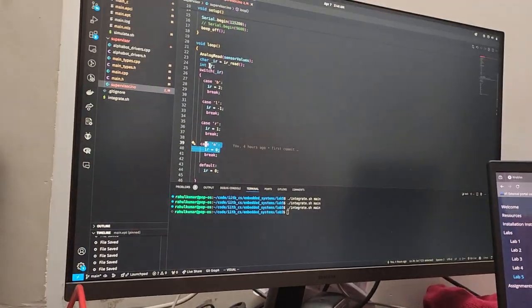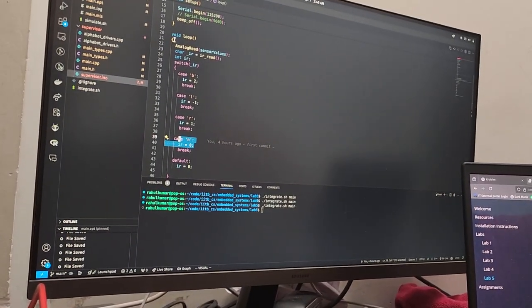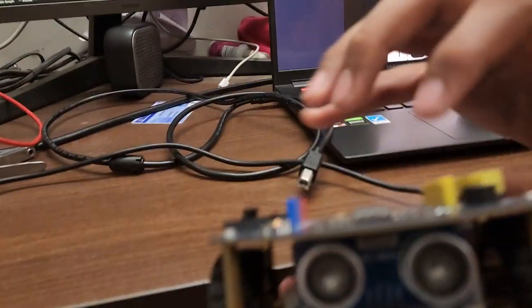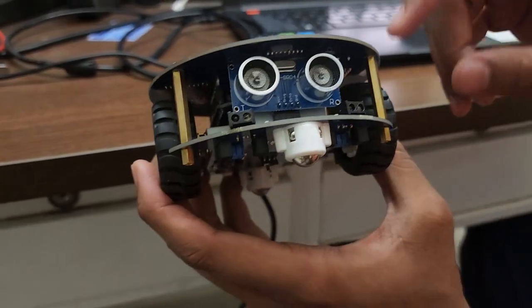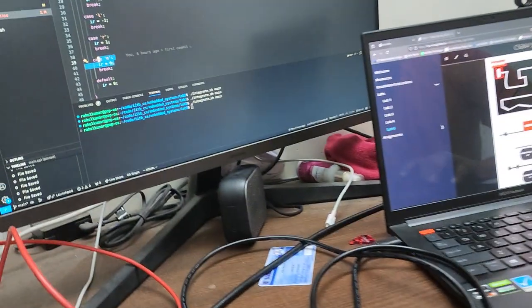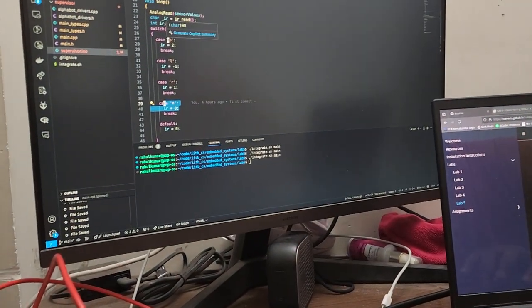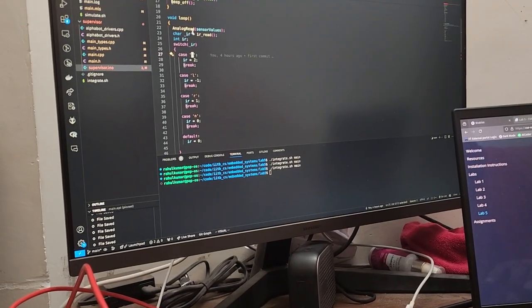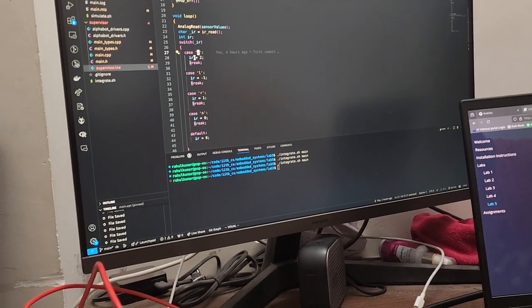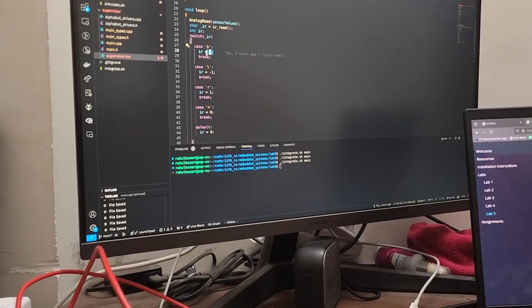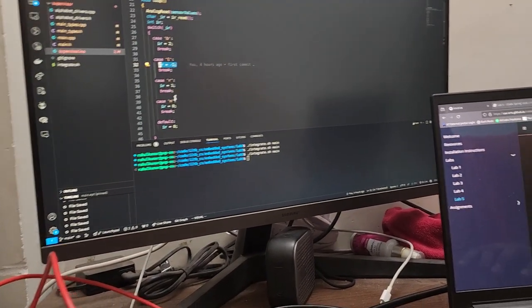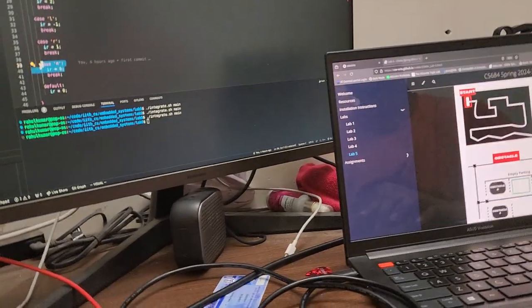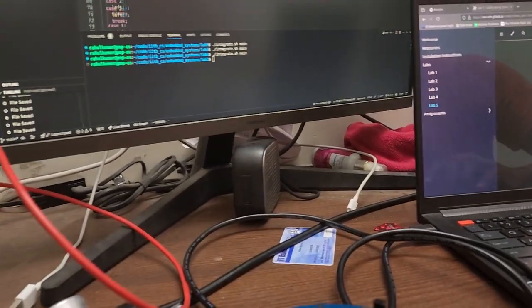Over here in supervisor.ino, this is the ino file which will be dumped on the bot, and we are not using any other sensor, we are just using what was already provided. These 2 are the IR sensors for proximity checking. Now if the output of this sensor or the register is B, that means both the sensors are detecting an obstacle, we are assigning it IR equals 2. Similarly -1 for only left, 1 for only right, and 0 for nothing, so there is no object detection.